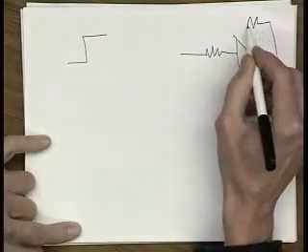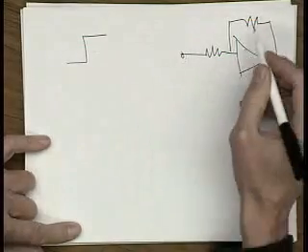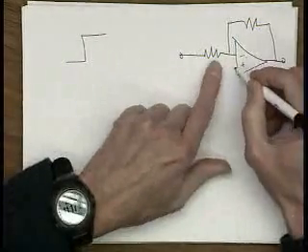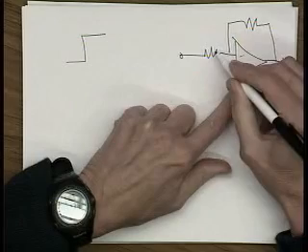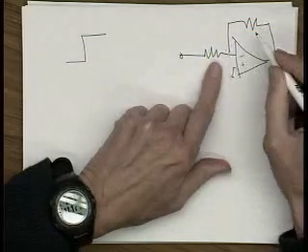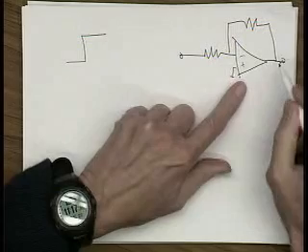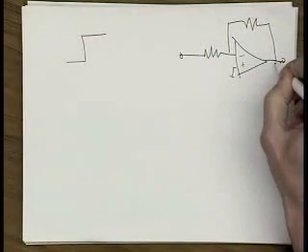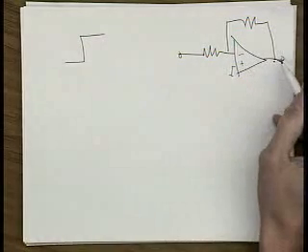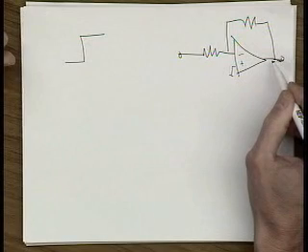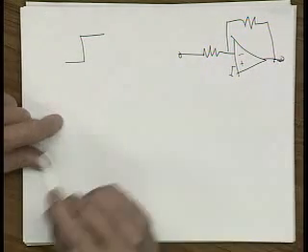Here's our circuit. Something to notice right off the bat is there's no resistor load, but the feedback network itself acts as a load, so don't ignore that when you're thinking about how the circuit has to work. Remember what we talked about: feedback loading acts as a load to your basic amplifier. So this has very close to the same issues you had with your earlier amplifier.